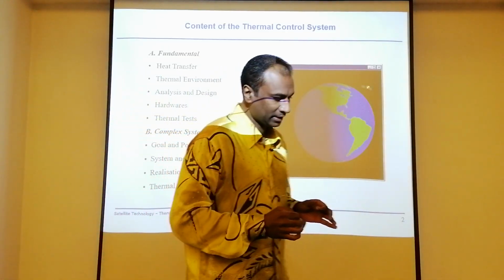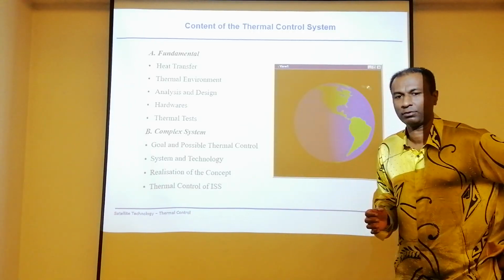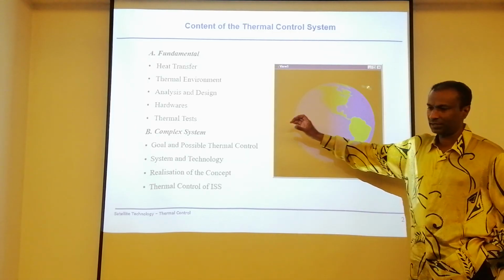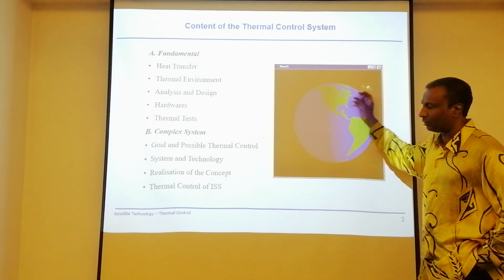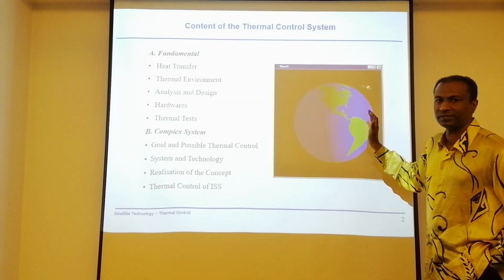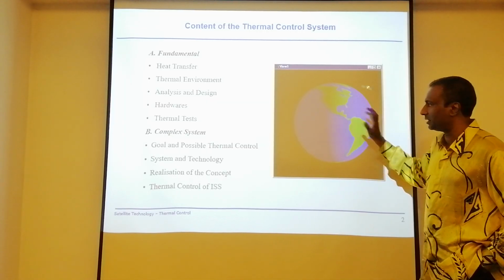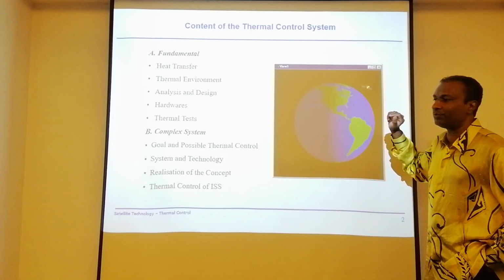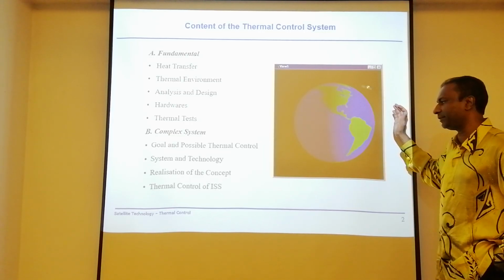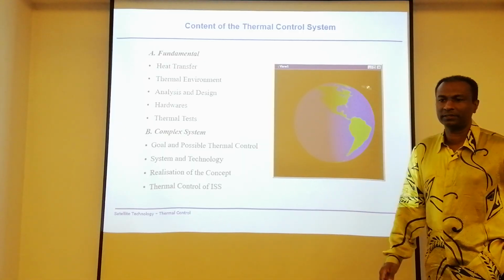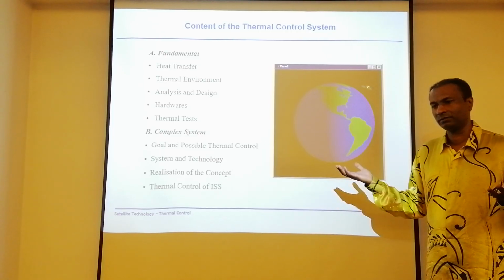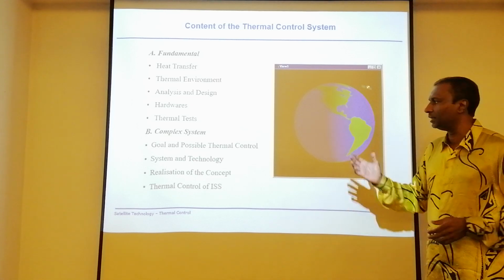Now, let's look at the typical condition that you always have. Assume that you have a satellite flying, an Earth-oriented mission, orbiting planet Earth. Typically, there will be two very visible conditions: the sun phase and the eclipse phase. As you can see, when the satellite moves into the eclipse phase, it gets very cold, and when it comes back to the sun phase, it's going to have a hot environment. So therefore, there's a cyclic effect of hot and cold throughout the orbit.